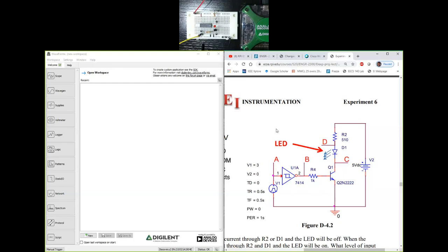So your white, sorry, the orange stripe and the blue stripe wires should be connected to ground when we do this experiment. And as you might imagine, we only have two oscilloscope channels provided by the analog discovery, and we have four measurements to make here. So we are going to have to split it up as a pair-wise measurement. So we'll do AB and then AC and AD. So three different plots for this particular circuit diagram. So there are three different circuits, but they're all related. So in terms of building the circuit, they're all the same, but with slight changes.